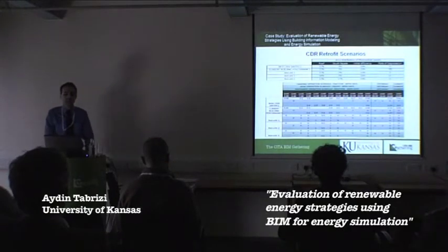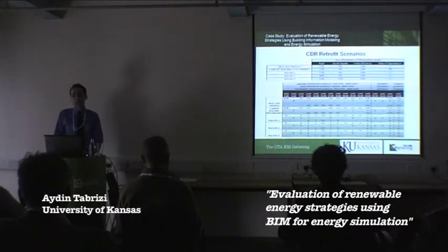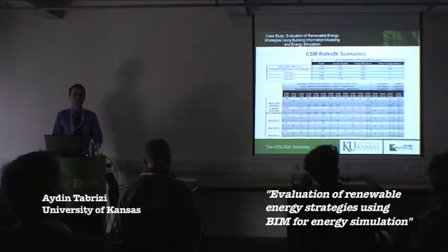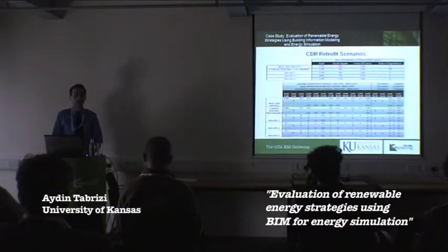And in the second table, the lower table, you can see the schedule for the operation of the lighting and also for the HVAC and equipment operation, where basically this building is an educational facility. We noticed that even though this building has been considered to operate from 5 a.m. to midnight, including weekdays, in reality we don't use this building on the weekends, and it is only used during routine office hours, which is 8 a.m. to 5 p.m. So basically we changed our retrofit plans for the equipment schedule to 8 to 5, with no use of the building during the weekends.